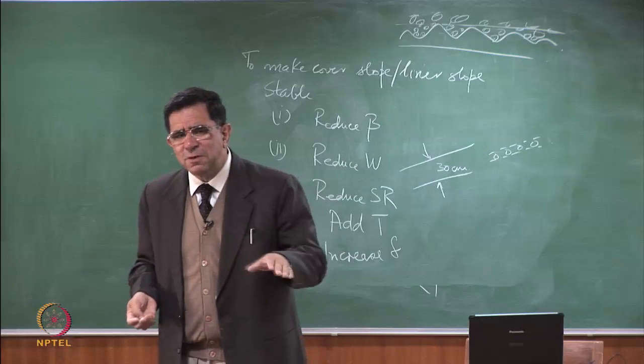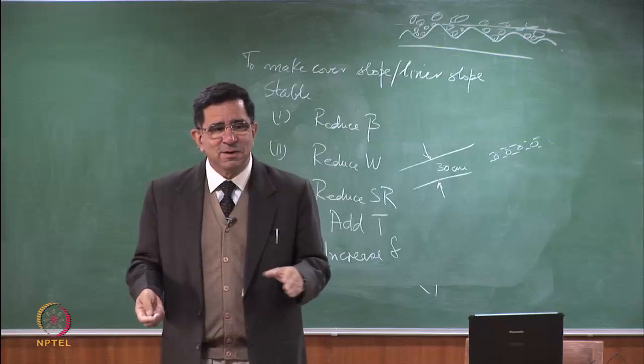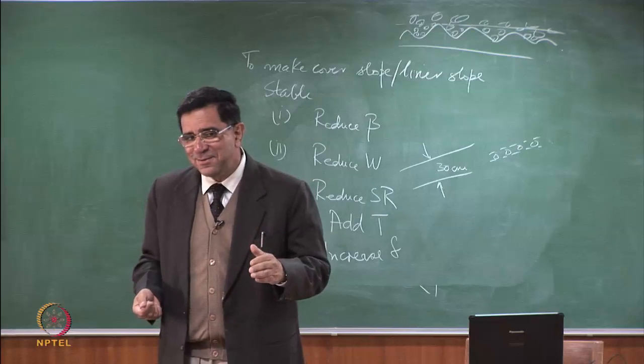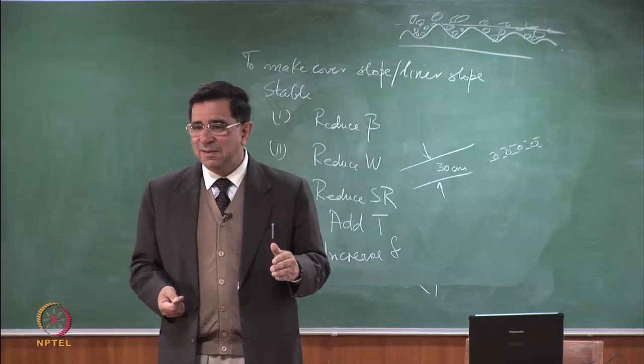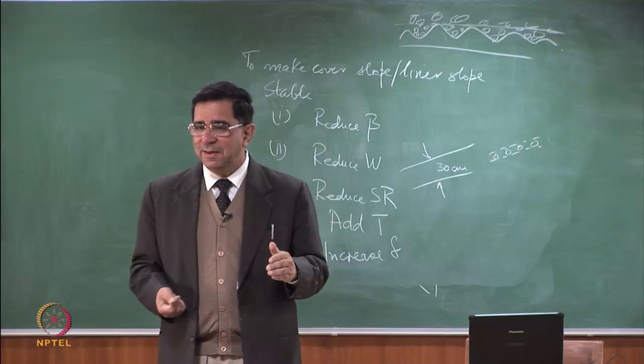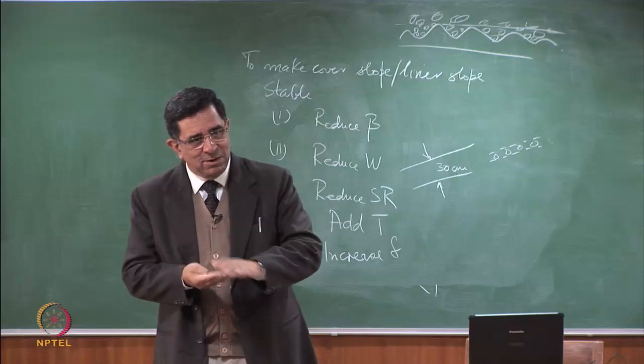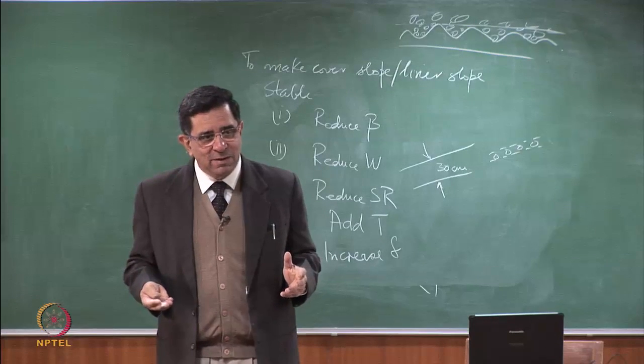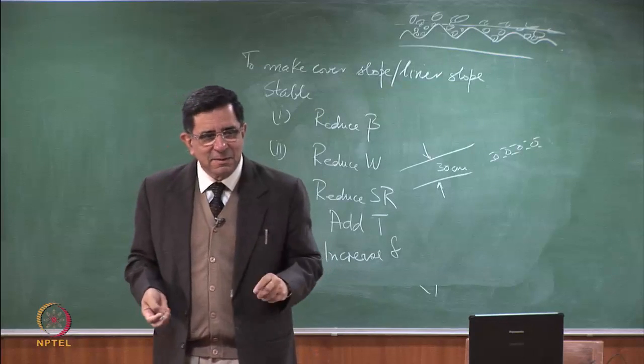Somebody will say, sir, I'll put some sand in between the clay and the geomembrane. How's that for increasing deltas? That's a jolly good idea. When you move the geomembrane on the clay, it's giving low delta. So I'll put some sand.